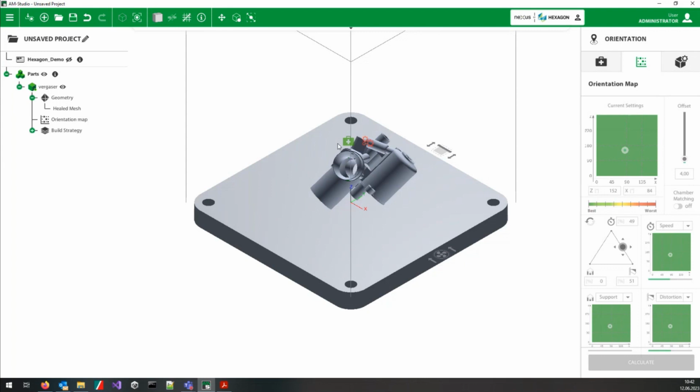Yeah, the machine-specific stuff is loaded, but all about the parts, the positioning of the parts, and also the supports is saved. The only thing which is not possible is keeping the build parameters, as the build parameters are machine-specific. So you have to assign new build parameters then, for sure. Okay. Understand. But all the geometrical stuff and support stuff will be transferred, so it's one to one.